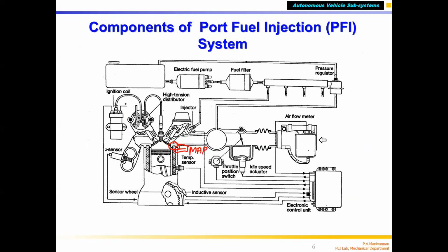You can do the simplest kind of speed-throttle control. What do you have? Throttle position sensor and engine RPM sensor. You have to create a lot of maps. I still want accurate control, because when the vehicle is going slowly, load increases, or heavy load is put on. Say an empty, unladen truck weighs maybe 2 or 3 tons when you did calibration. Then you add another 7 or 8 tons of load. When it goes on the same flat road, more fuel is needed, and more vacuum is created.